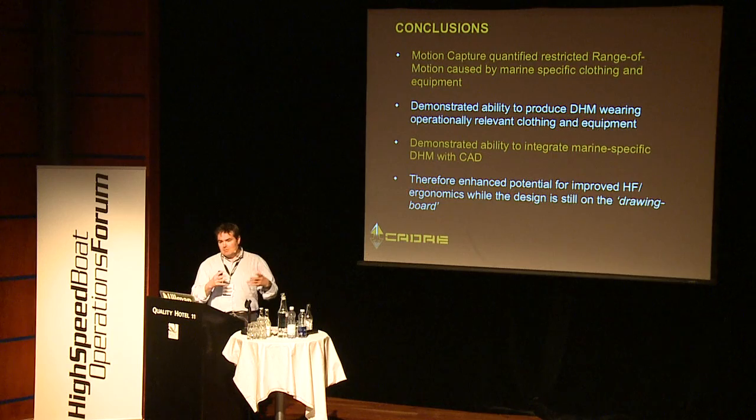So in conclusion, we were able to use some of the motion capture technology to look at, yes, we can see there is a difference, and we can actually measure that. The digital human models, you can get into the CAD environment and be very almost marine specific as to how much space we need to leave for people. And so this tool does mean that you can get a better indication of what that real person is like whilst the designs are still on the drawing board, and actually design from those people with the command and control and the seating, and design out from that rather than designing the boat and then hoping that that person with all that equipment on will still fit and get in and out of the craft effectively.